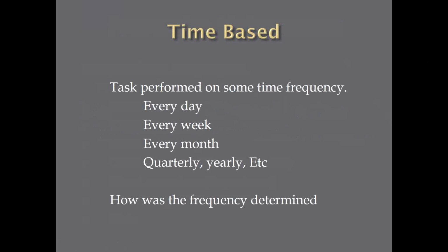Well, the time-based PMs we talked about, they're PMs performed on some time frequency. We may do them every day. We may do them every week, every month. We may have quarterly PMs we do. Some PMs we do yearly. That's the only time we can open the equipment up, or on our scheduled annual outages. So there's all kinds of time frequencies we use on PMs.